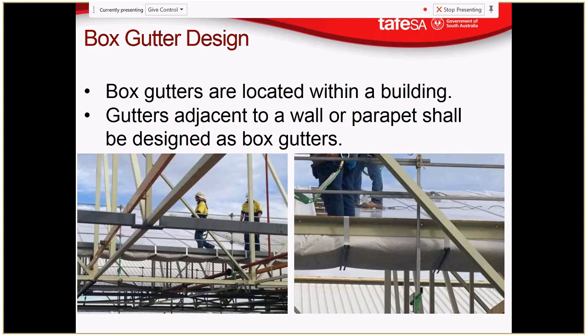That's going to be possible if it's a gable-ended roof. If it's a hip-ended roof with a gutter that extends all the way around, it's probably not going to be an option, because if we're joining our gutters to existing gutters, we want exactly the same cross-sectional area of gutter all the way around the house. Otherwise, we just get some really funky details in the gutters there.